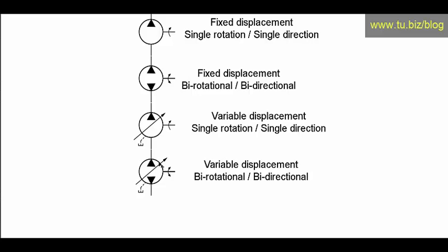Many pumps can have bidirectional flow, where the flow can come in and out at either port, and the shaft could rotate only in one direction, and you still have the ability to make the fluid go from one side or the other. This one is drawn with a birotational, but it doesn't always have to be that way.